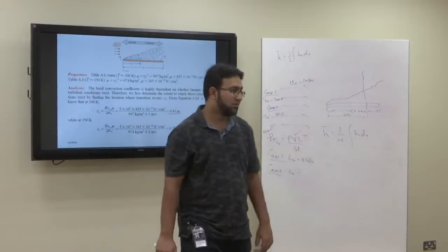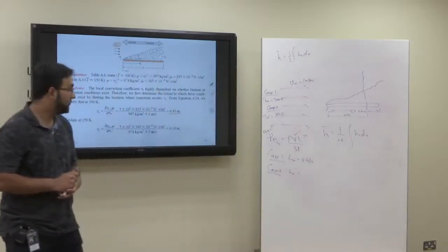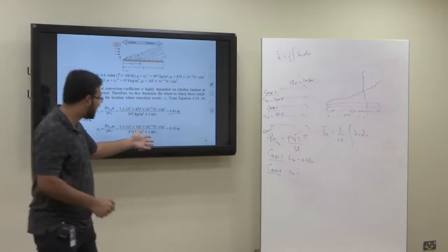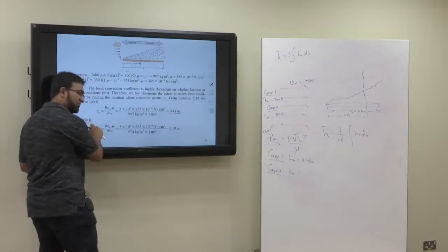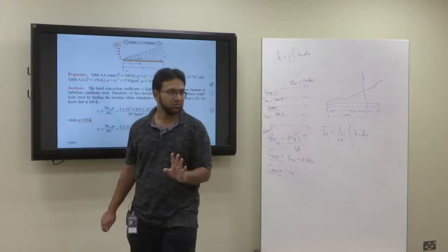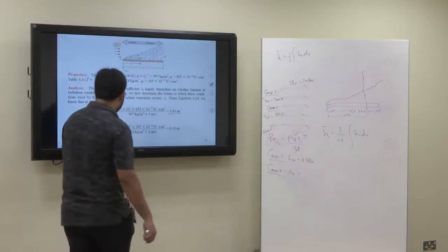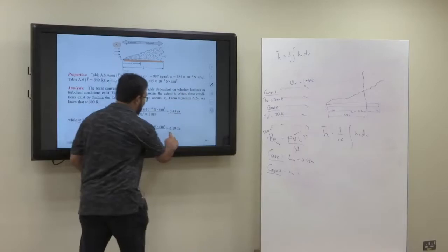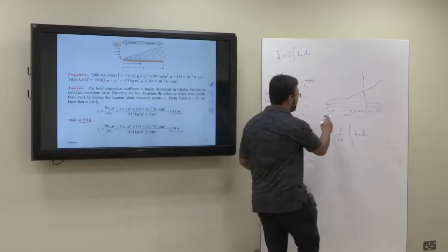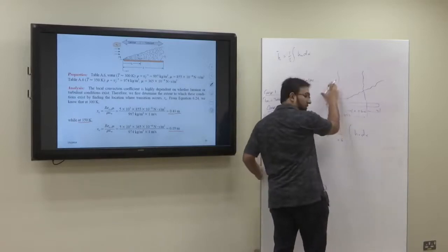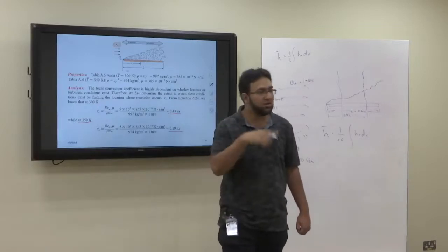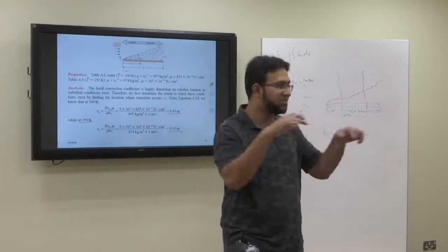Yeah, but we have different temperatures, 2 cases. The other case we have not yet solved. So now we put the values for the other case. For the other case, density and viscosity will change; other things remain the same. Once you put the values, you find that L critical is 0.19. So in this region you have laminar, in this region you have turbulent. So in both cases we have laminar and turbulent flow present over the entire plate.